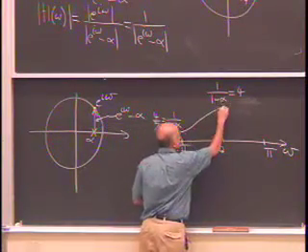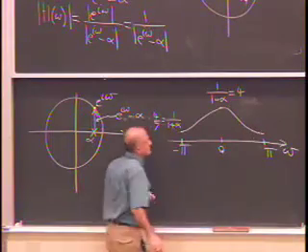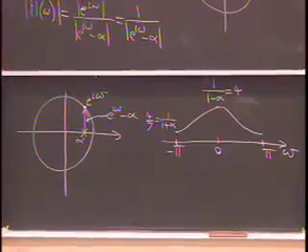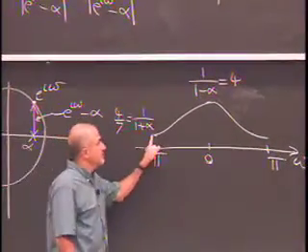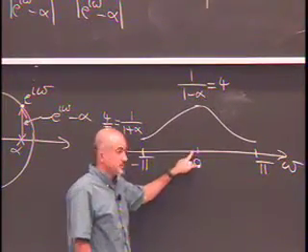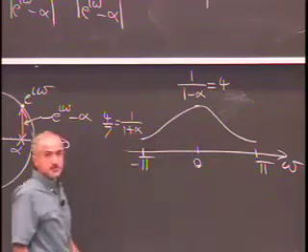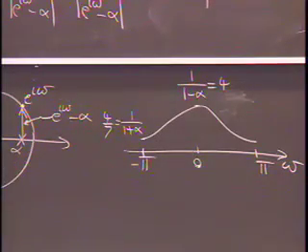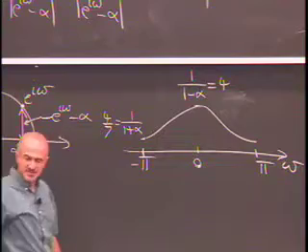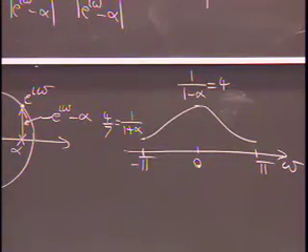Now, to get the concavity, you just plot a few points and you get the concavity right. But the basic idea is to recognize that this filter favors lower frequencies, and this favors the highest frequencies. Everything is symmetric about 0, so that's how you get the fact that this plot, which I have not drawn to be symmetric, is symmetric. What kind of filter is this? Low-pass filter.